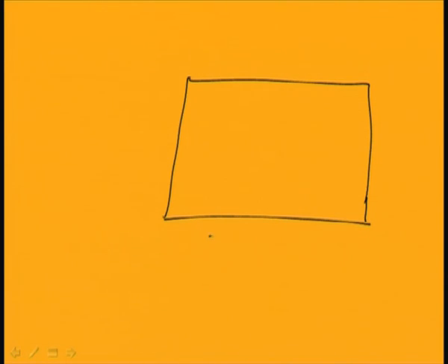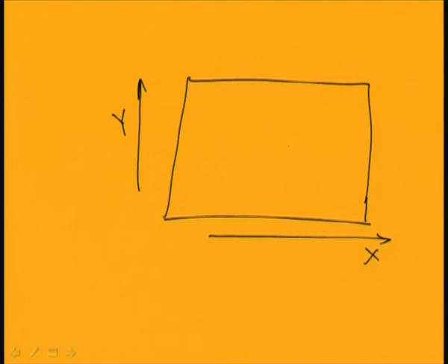In this case, the vibration may take place in the x direction, or in the y direction also. If you have a thick plate, the vibration may take place in x, y and z directions, but in case of a thin plate you can assume that the vibration takes place in the z direction, and this transverse vibration in the z direction will vary along the x axis and also along the y axis, but we are limiting our study to only one dimensional systems like string.